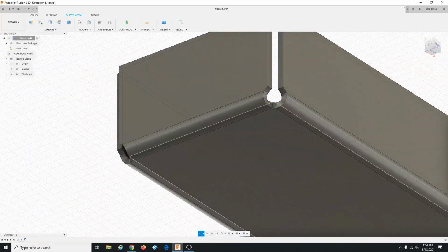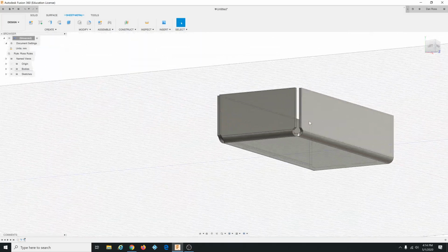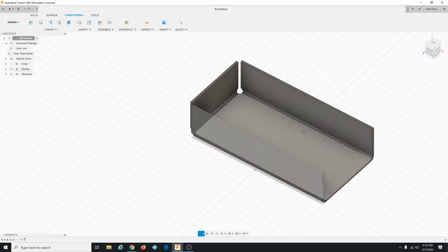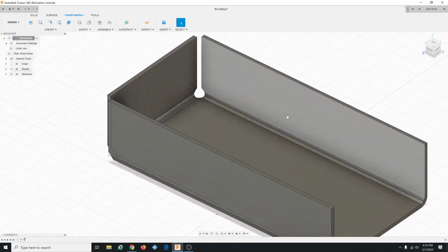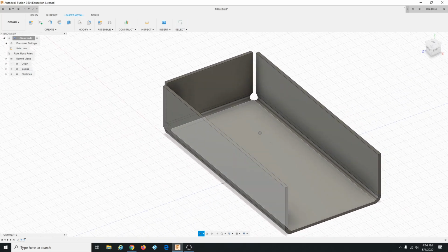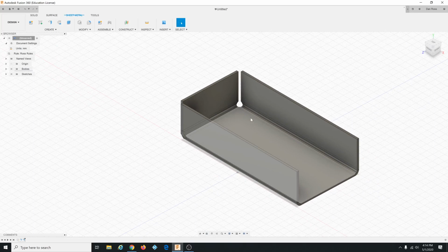See? Which is easy to make with a drill bit, like I say in the pattern. You just drill a hole at the 4 corners. That's what they usually do. Or they do a lot, not always, but especially with aluminum, like high hardness aluminum, like is used in airplanes. They use very hard grades of aluminum that are prone to cracking. So one of the things you can do to reduce cracking is use a lot of rounded radii. All right, there's that thing.